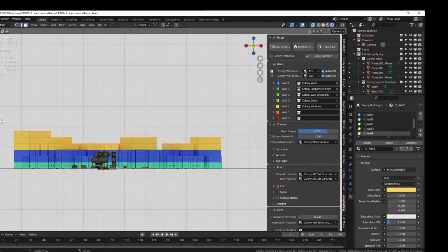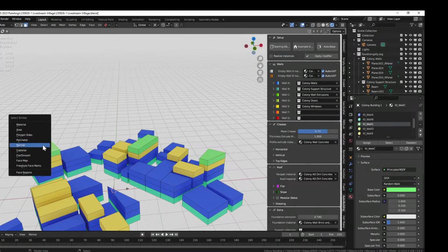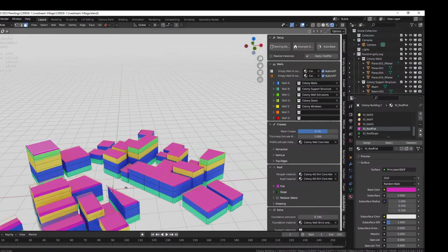Then I'm going to grab these, and these, and I'm probably going to change this around. And sure. We'll do this to start with, just to get us something. And I'm going to convert those to extrusions. And then I'm going to take Shift-G, normal, grab all the ceilings, the roofs rather, and get the roof flat.